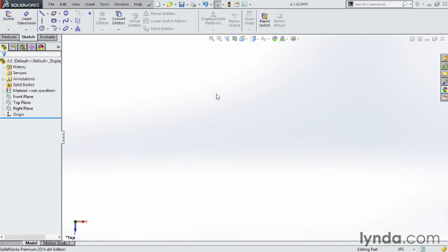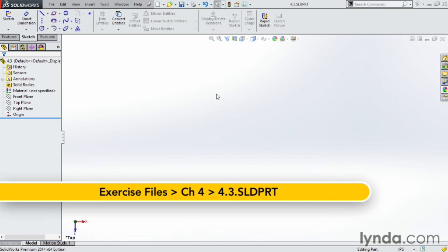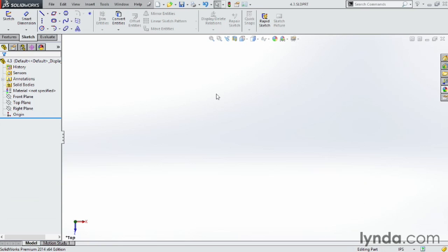Splines are the ultimate free-form curve tool. Smooth flowing shapes and wild curves are the results. However, be careful. Splines are very difficult to relay on drawings, and manufacturing is more of an issue. Sometimes the best choice is to use a spline as a layout sketch for traditional arcs to get the best of both worlds. Let's take a look at some of the tools within the spline command.